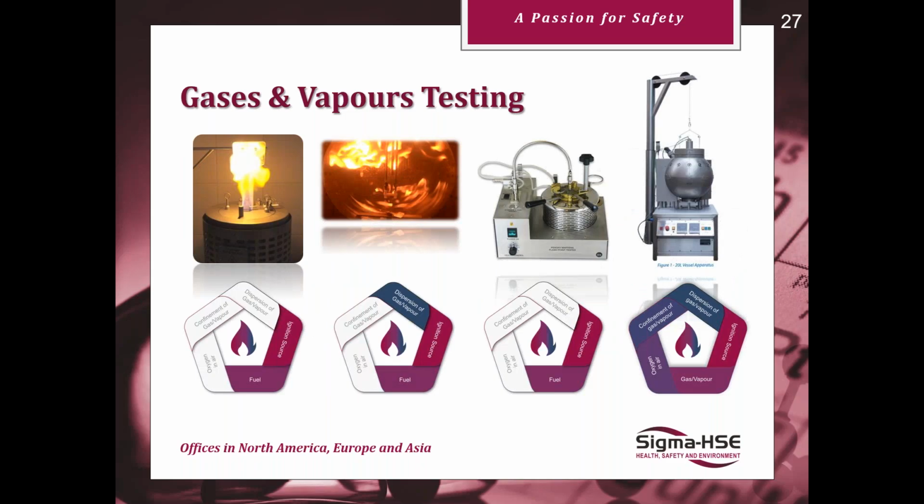So here we can see photos of some of these tests. Starting from the left, we can see the auto ignition temperature equipment, whereby you inject a known volume of sample into a round bottom flask situated within an oven. The sample will vaporize, and if the temperature of the oven is hot enough, the vapor will then ignite, and we can see that here.